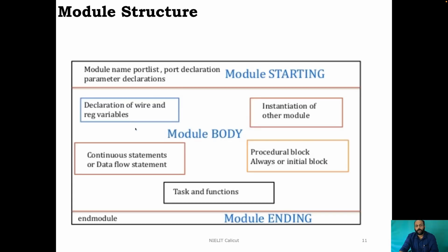So if you look at what should be inside the module description, a module will always have the keyword module. There will be a module name, which is a user given name. You can give it any name, but a module name should not start with a number or a special character.